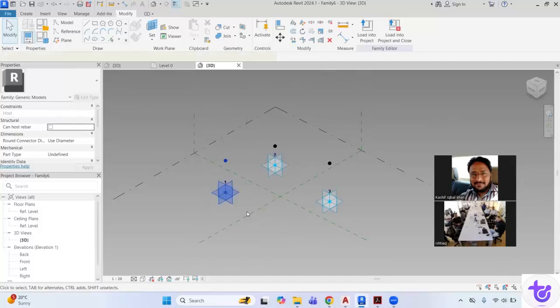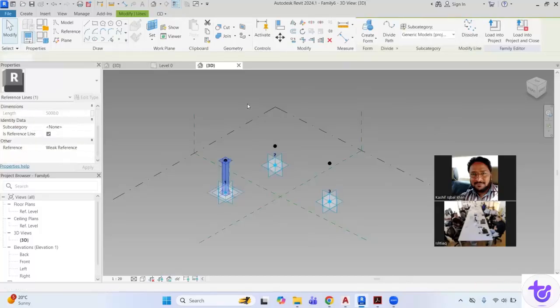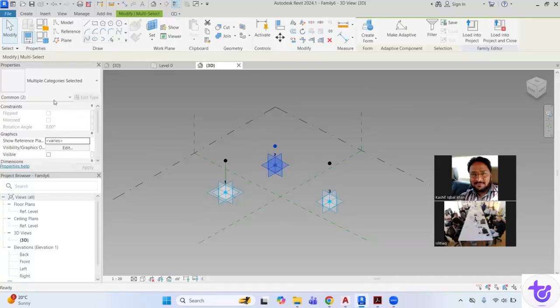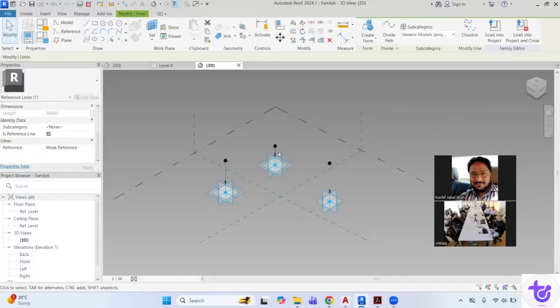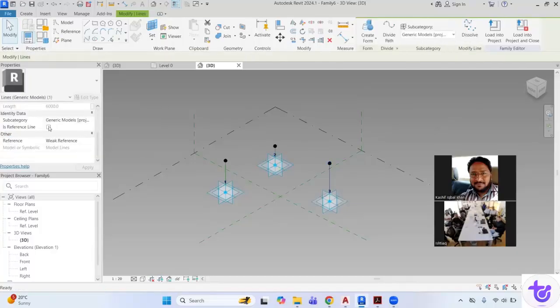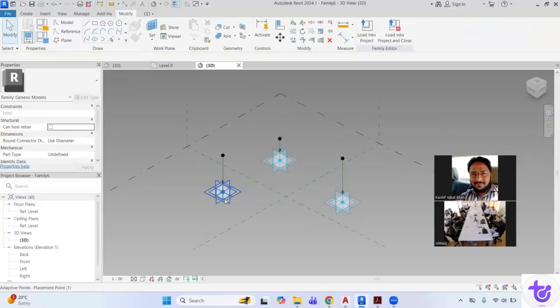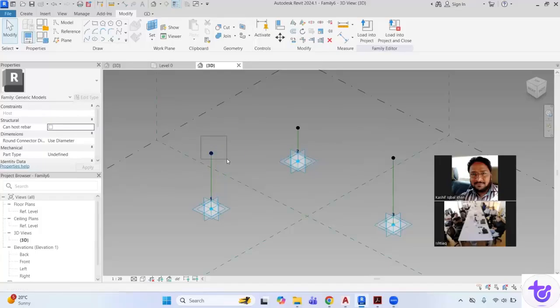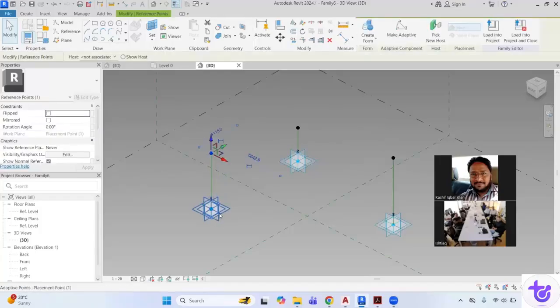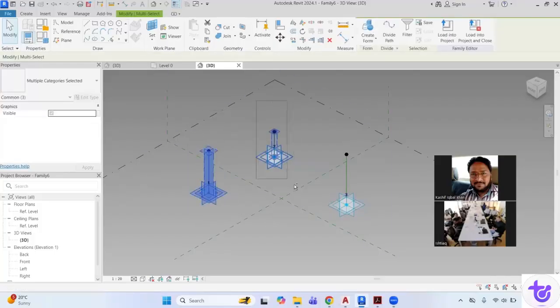And then selecting these two and then have this as a reference line. This is step 3. Have this as a line and then make it as a reference. So these are the 3 steps. First one, having the 3 points, make them adaptive. Second is taking the reference point by selecting their respective adaptive points as a work plane. And then again join them as a reference line with a spline. Now just select this, and this.